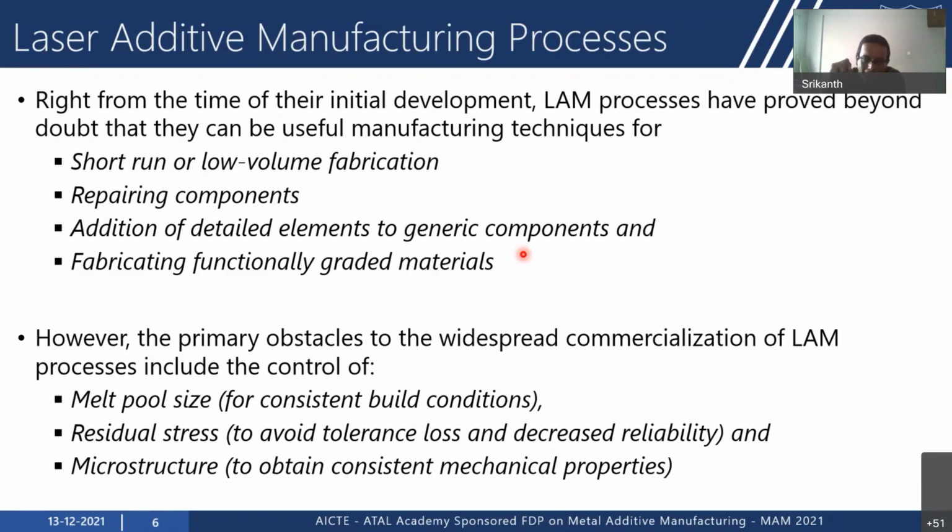However, if you look at some of the obstacles to the widespread commercialization of these LAM techniques, one is the control of the melt pool size. As I said earlier, multiple beads will lead to a track, and the bead is formed from a melt pool. So the control of melt pool size is required for consistency in the build conditions. The build conditions change depending upon the location of the deposition.